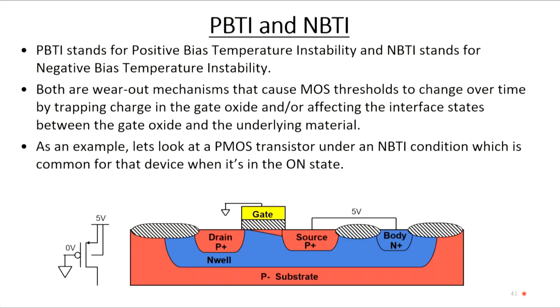Switching gears yet again, PBTI and NBTI. This stands for positive bias temperature instability or negative bias temperature instability. And both of these are wear-out mechanisms that cause MOS thresholds to change over time by trapping charge in the gate oxide and/or affecting the interface states between the gate oxide and the underlying material.